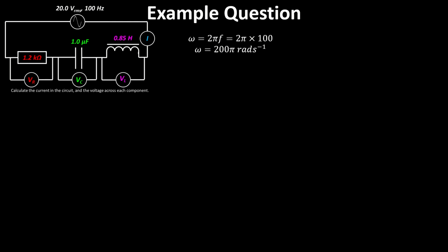So first of all, I want to calculate... well, we don't need to calculate resistance because we know what it is. Okay, so I'm going to start putting these into a phasor diagram. Now the resistance phasor is at 3 o'clock, and we know it's 1,200 ohms.